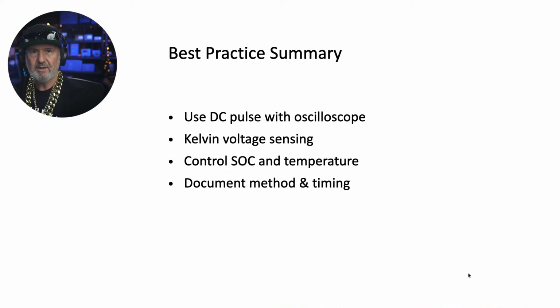So best practice is to use the DC pulse with an oscilloscope. Make sure you're using Kelvin voltage sensing, control the state of charge and temperature, and if you're really scientifically minded, document everything, your method and timing. There you go. So now you're a qualified cell tester.